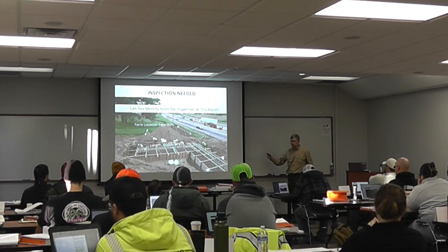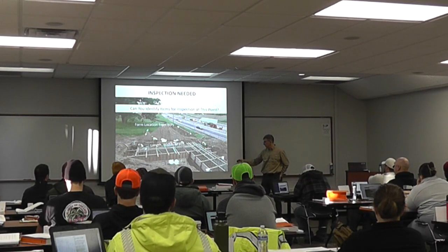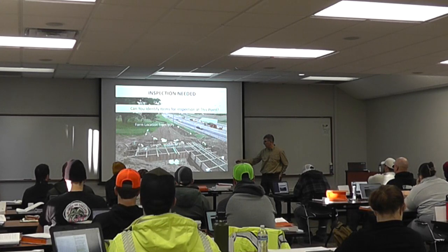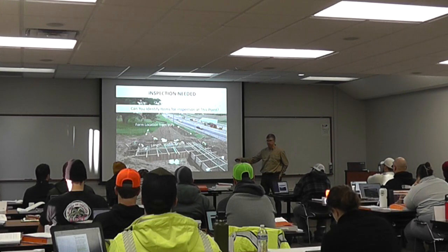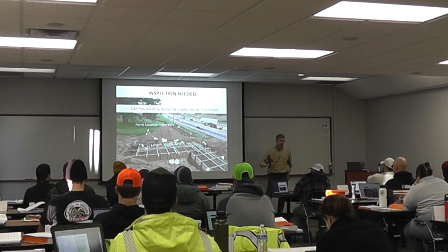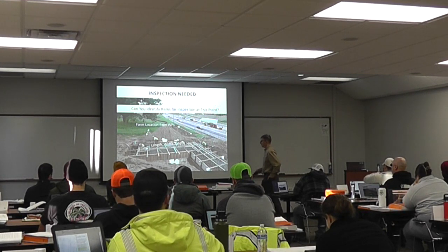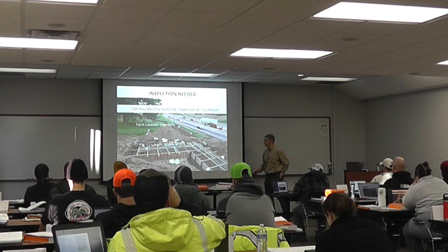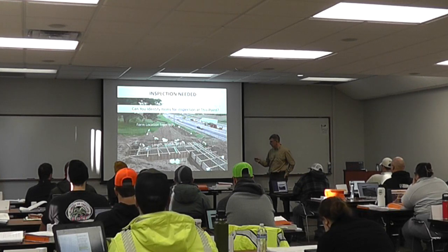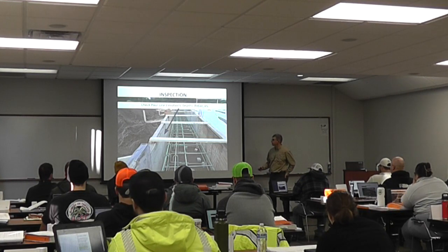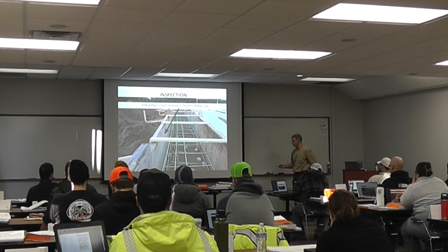Obviously, it's always better to be out here when they're doing it. So, for instance, if this inner form somehow was a foot off, and now they had to move it once you're at this stage, it's much harder to move it now than the day they put the forms up there. So the more you can be out there watching the operations, doing your checking, the better. It helps the whole process. So again, looking for the stakes, offsets from working points, is the rebar in the right location? Checking pour line elevations, depths, rebar placement, and so forth.